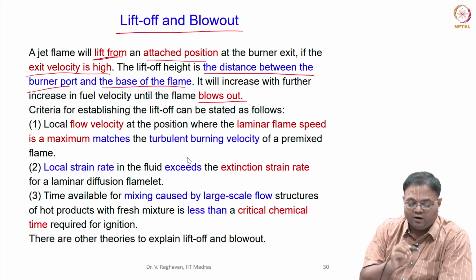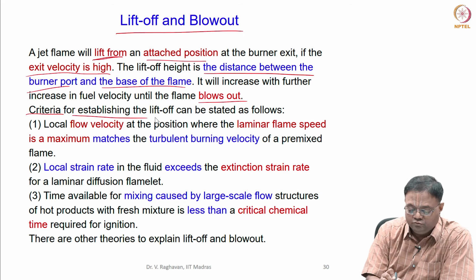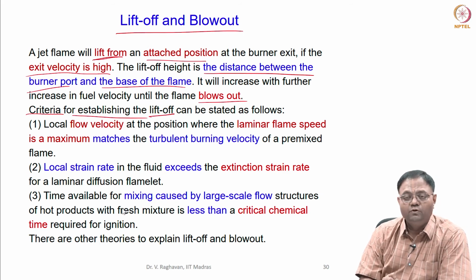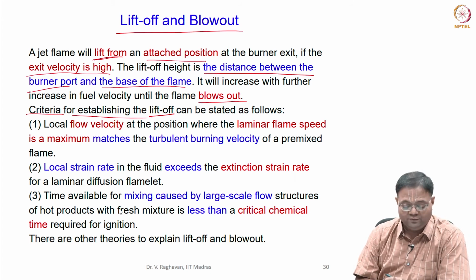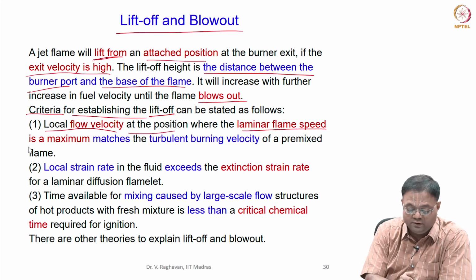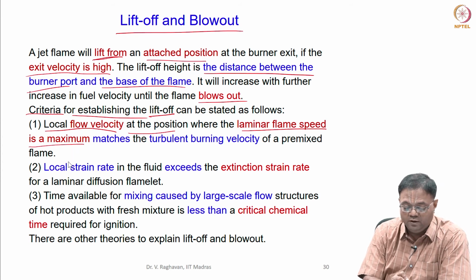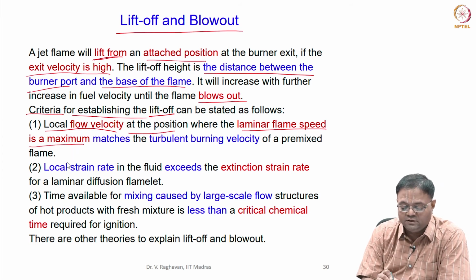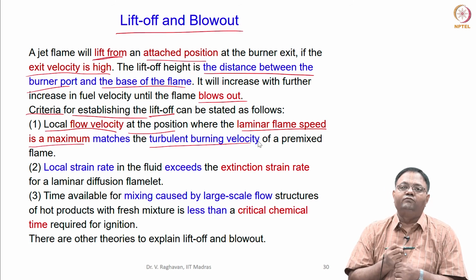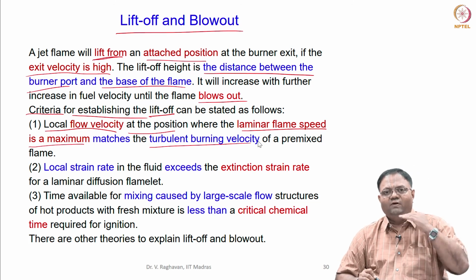So now, what are the criteria? Some theories to establish the flame liftoff. There are three arguments. The first one is that at liftoff, the local flow velocity at the position where the laminar flame speed is the maximum will match the turbulent burning velocity. So that is the liftoff position. When the flame is lifted off, where will it stand?